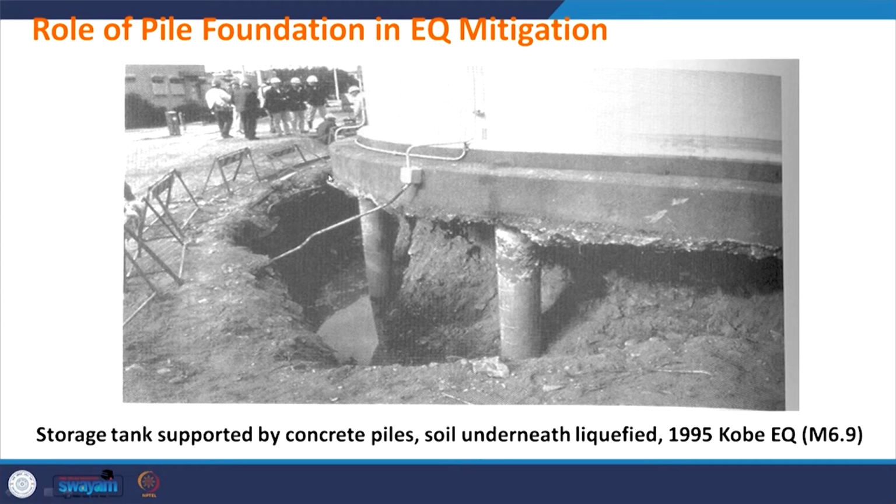However, there was no damage to the tank, and the reason was that this tank was situated on pile foundations and the piles were passing through the liquefiable soils, but resting on the hard strata.